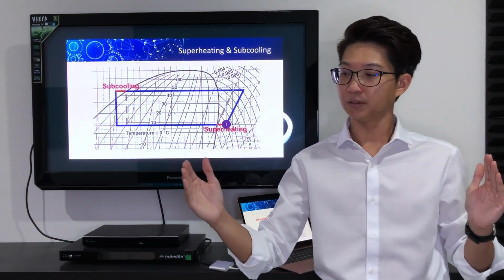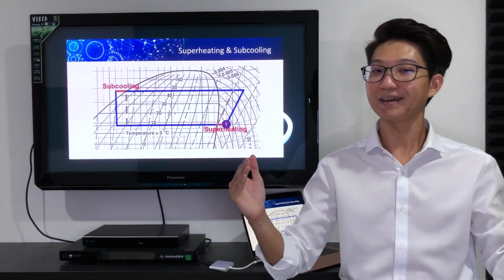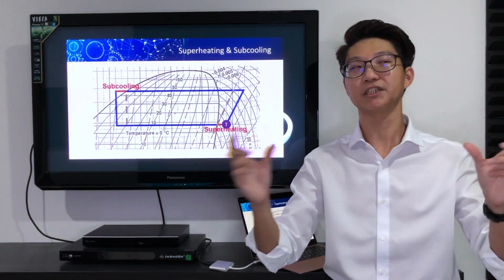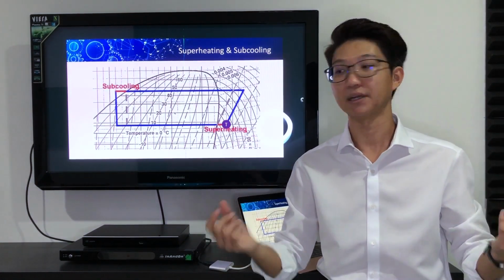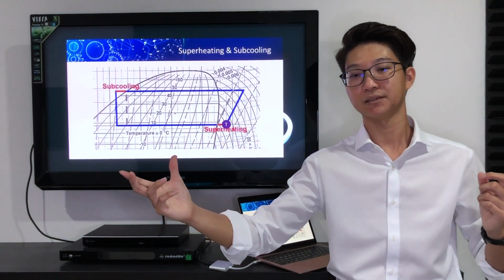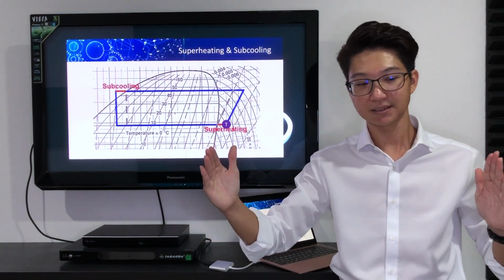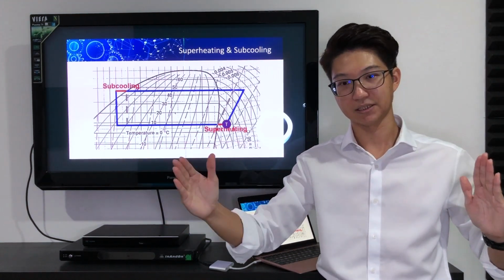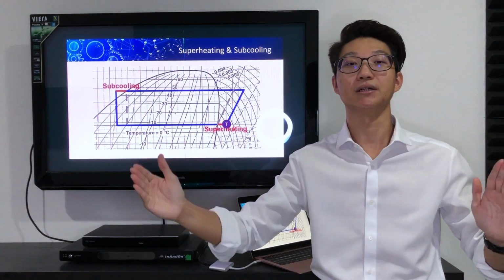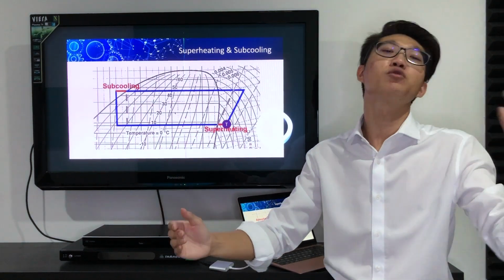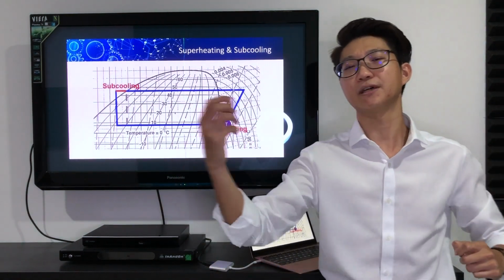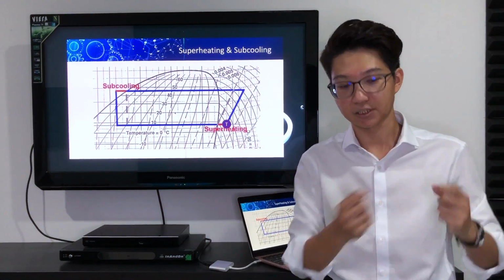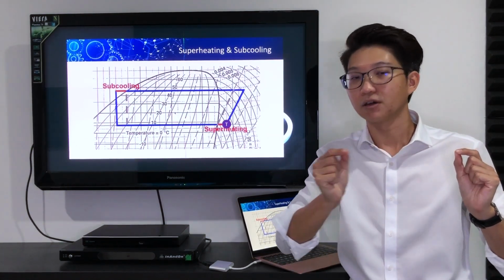Meaning, it didn't enter the superheat process as much as we expected, right? It delayed the process. That means the phase change process is longer than we expected, the evaporation process is longer. What do you mean by longer? That means you have too much refrigerant, or you have not enough cooling load, not enough heat for the refrigerant to absorb. That's why the boiling process is very long.